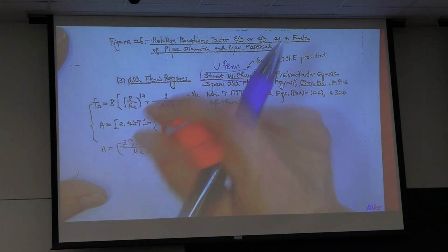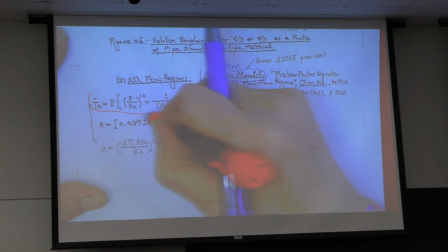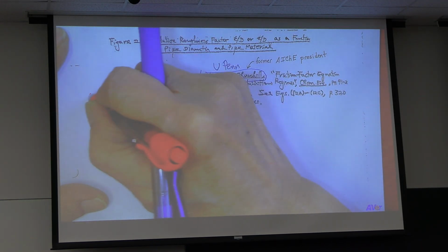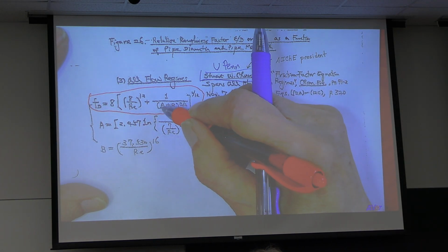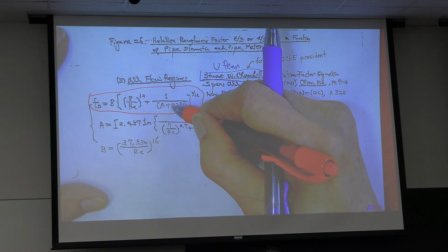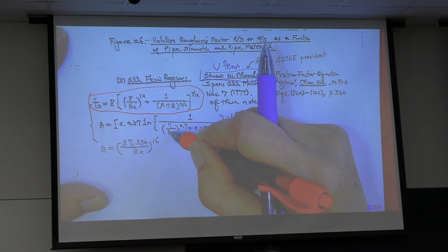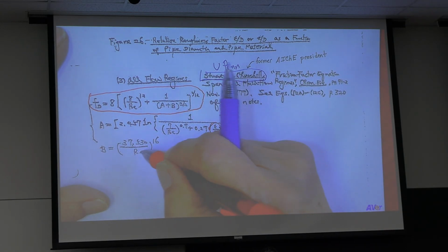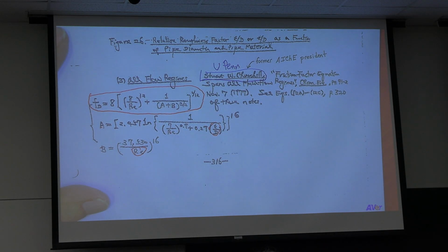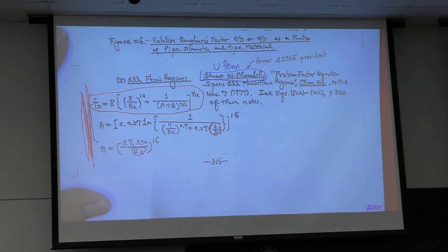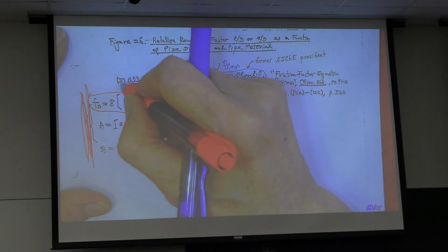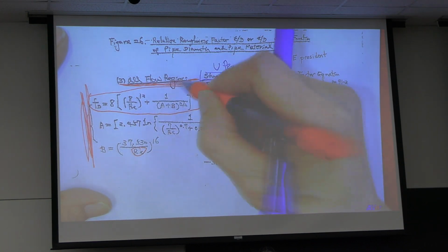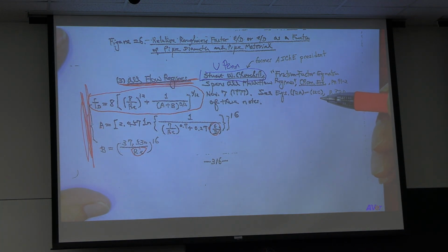He gave a Darcy friction factor correlated with Reynolds number, constants A and B. A involves Reynolds number and roughness. B, Reynolds number. This is for all laminar and turbulent flow. Claimed to be the best to use.